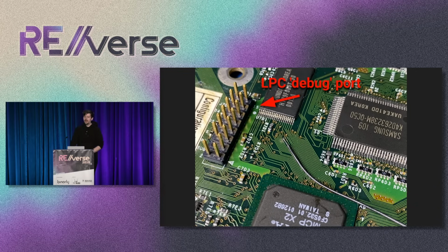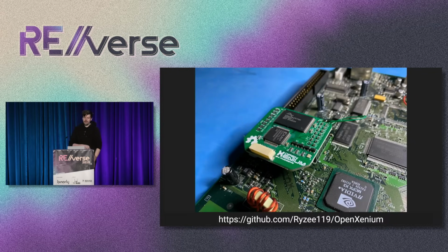And this is all just getting familiar with soldering, using flux, cleaning up the board with isopropyl alcohol and stuff like that. And being able to install pin headers is a big, common skill of basic hardware hacking, be it playing around with Xbox, or if you're researching some device that has an unpopulated debug port, you're going to want to solder a header on there so you can easily put logic analyzer probes on it or do other things with it.